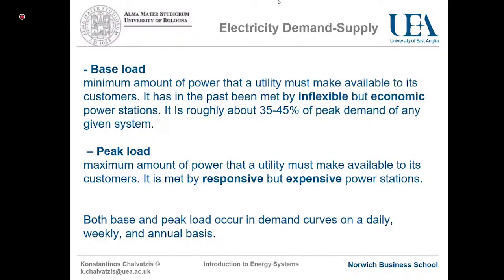There's always some demand, and it is at least that level of demand which we tend to consider as the base load, a demand that we always need to be there. And typically, historically at least, we have tried to cover that demand with power stations that are reliable, so they can be trusted to produce energy when we want it. And ideally, they're as economic as possible, simply because that's electricity that we need to produce all the time. We ideally want it to be as low cost as possible.